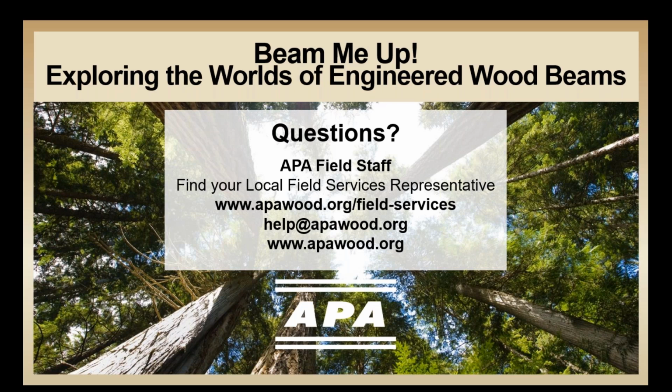Great, thank you. Another question that came in is about treated products. Do treated products require special connectors? It depends on the treatment a little bit. So if I start at that use classification 2 with the borate treated LSL, used in a dry use environment, that doesn't require any special connectors.